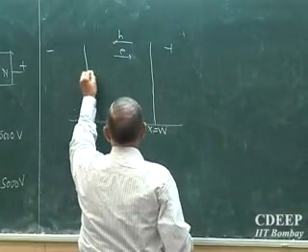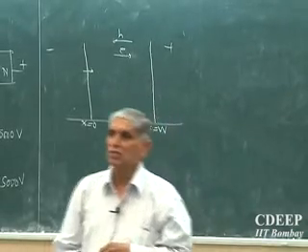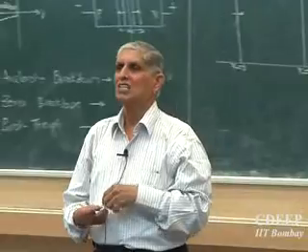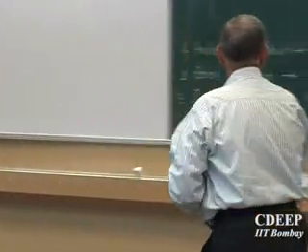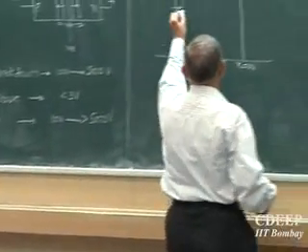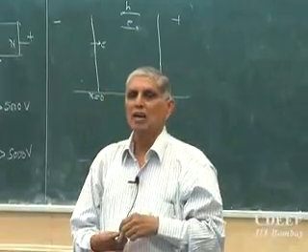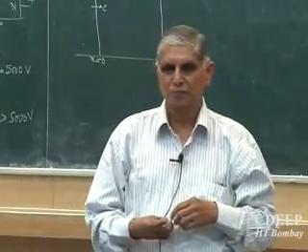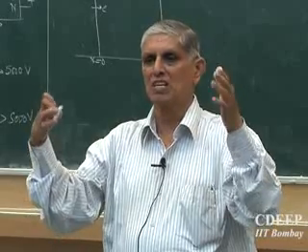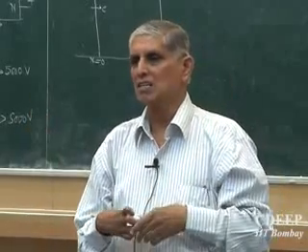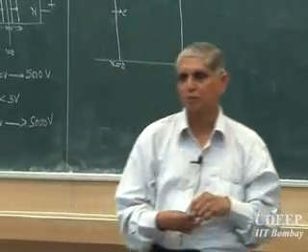So as soon as an electron enters from say the P region into the N region, or is thermally generated in the depletion region, with a large electric field present it will acquire sufficient energy. If you have a larger electric field, the force acting on it is Q times the electric field. Larger the electric field, larger is the force, which means larger kinetic energy is picked up.